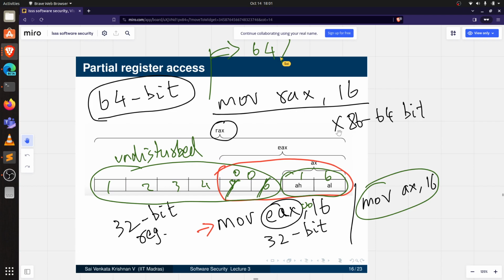Whenever Intel upgrades its ISA and increases the register size, it doesn't want its loyal customers' old code bases to become obsolete. To enable easy portability and execute the old code on the new systems also, it allows partial register access, mainly for compatibility reasons.